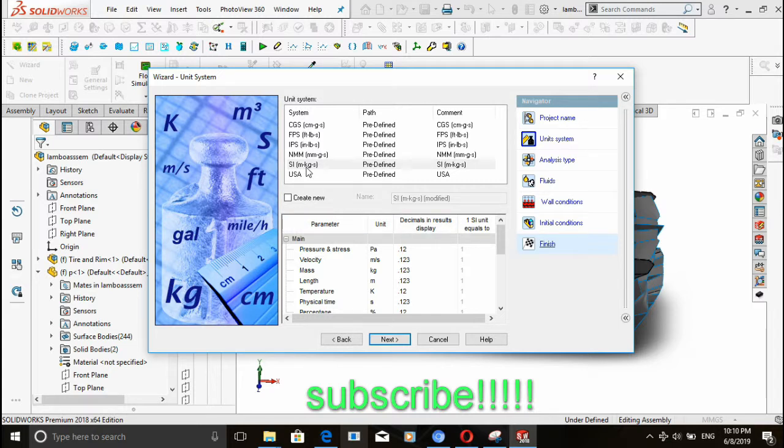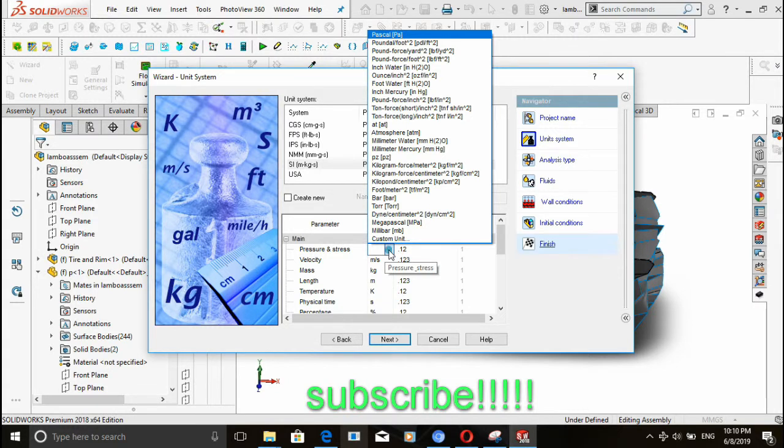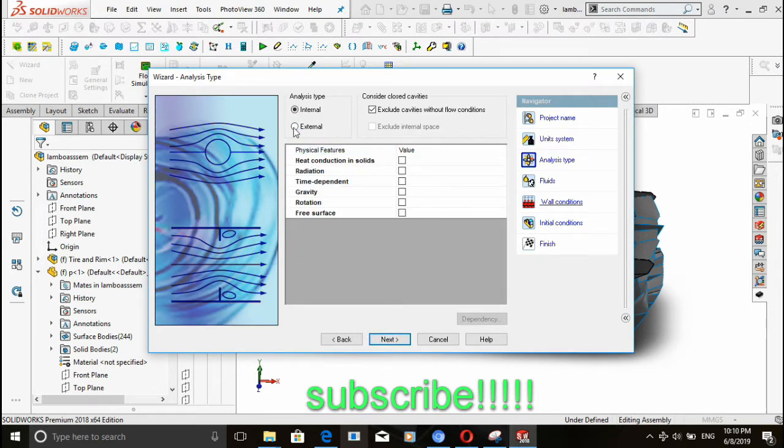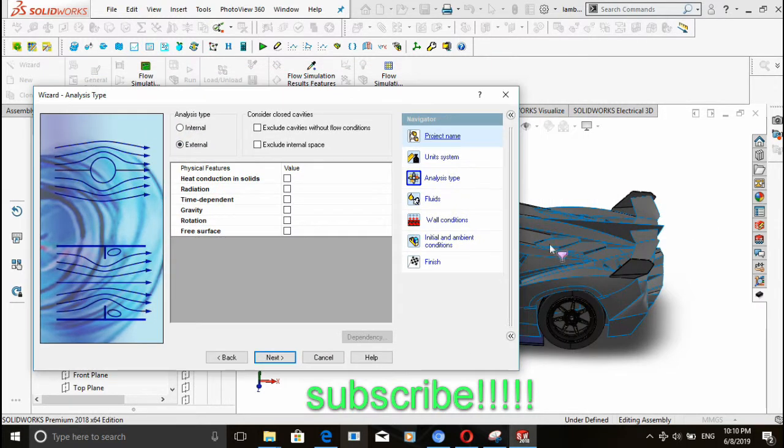So it is meters, kilograms, and seconds. If you wish, you could change it. This is pressure, which is in Pascal, and here the velocity, you could change it to maybe miles per hour, but it's meters per second. It's okay. So all you need to do is continue. So you're just going to click next. Now at this level, I'm just going to take external analysis. We're going to take external analysis of the car. So we're just going to take exclude cavities without flow conditions, and exclude internal space. Once this is done, we're just going to continue.